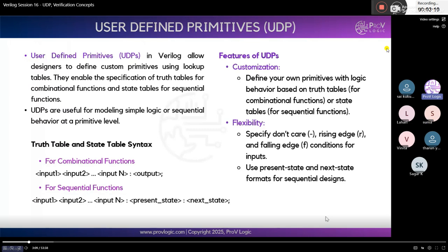And today we are also going to start with the test bench concepts. You have already developed a lot of test benches, with initial blocks and always blocks, dollar display, dollar monitor, dollar finish, and to open the waveforms, dollar dumpfile and dollar dumpvars. But we will discuss these in more detail: how they are used as simulator directives, and how a test bench can be written in different ways. We will discuss this in today's session.